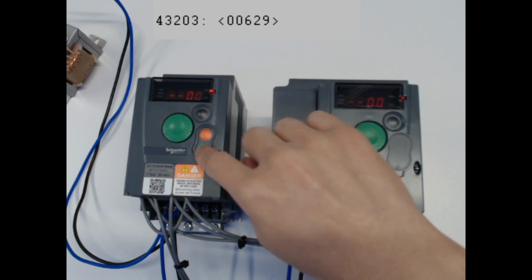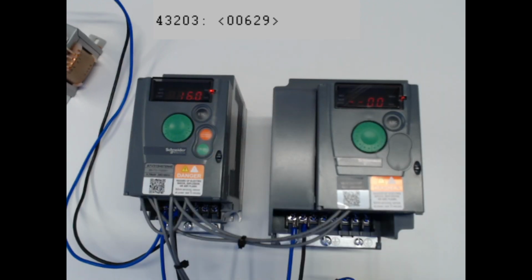So once I press run, the inverter will go up to 30. This is my low speed. Remember, I set it such that the speed of the pump cannot go below the low speed. Now, the low speed has a delay timer as well, where I set it at 10 seconds for the purpose of the demo.